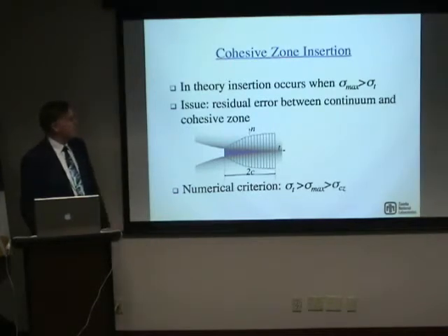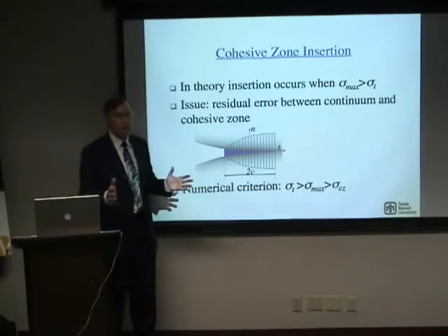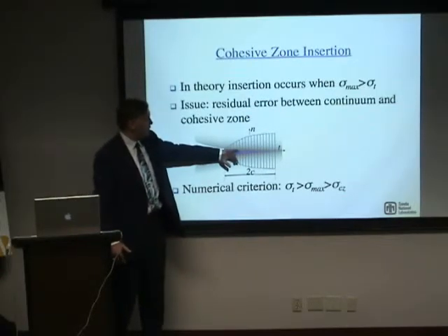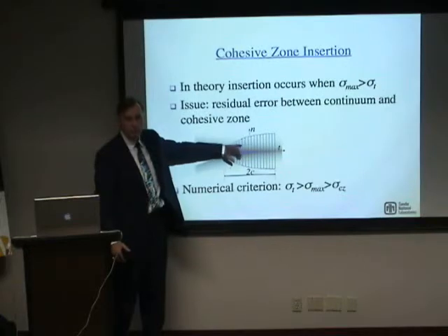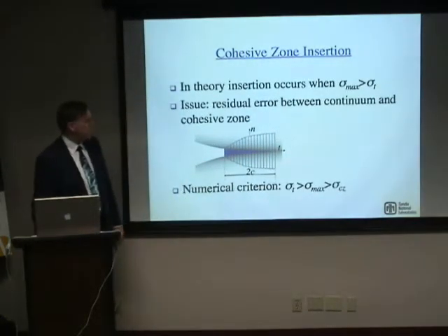Another issue that comes in here is that we have a discontinuity, as we talked about earlier, between elements. Well, we also have a discontinuity in the stress field between the cohesive zone and the continuum. And as such, we tend to weaken the criterion for when to initiate a crack below the tensile strength.